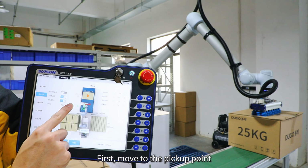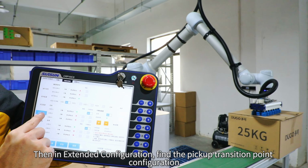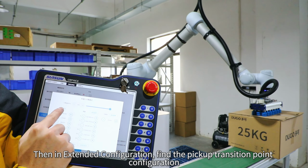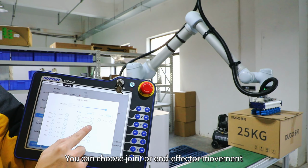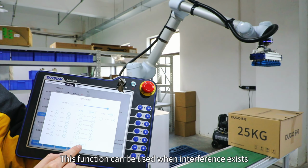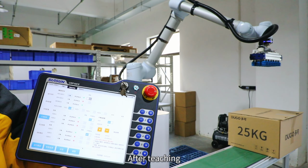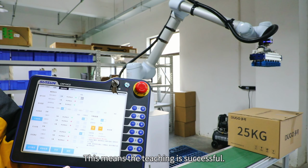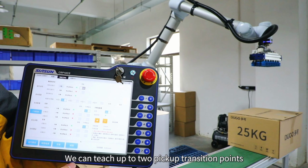First, move to the pickup point. Hold to move. Then in extended configuration, find the pickup transition point configuration. You can choose joint or end effector movement. This function can be used when interference exists. After teaching, click Record Current Point. This means the teaching is successful. We can teach up to 2 pickup transition points.